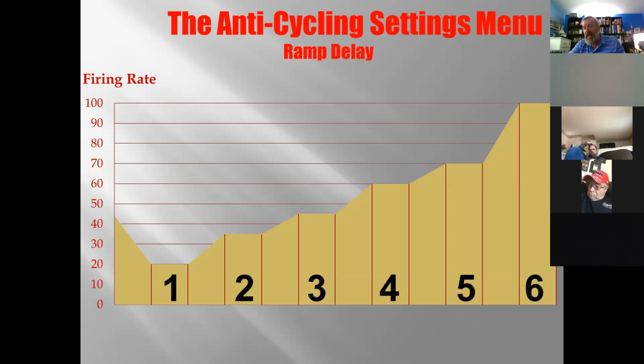If you're asking us, how long should my boiler run every time? We like to see no more than 6 cycles an hour. So that's 10 minutes. Set stage 1 and 2 for 5 minutes apiece. It's going to give you your 10 minutes of runtime, and then let the boiler go. But it'll hold it back.